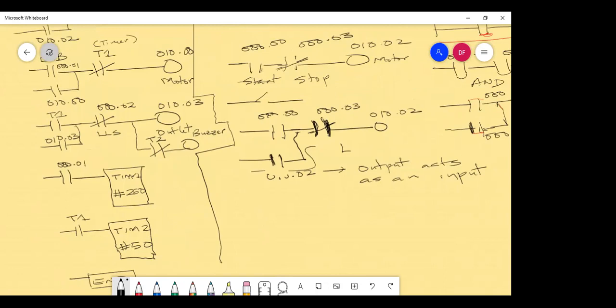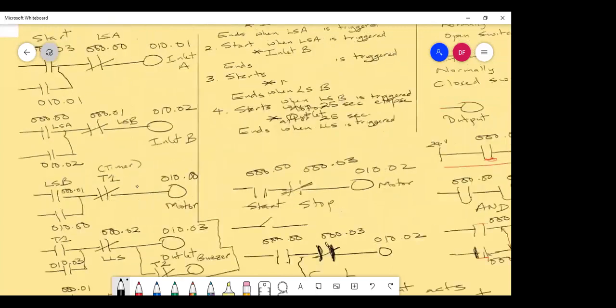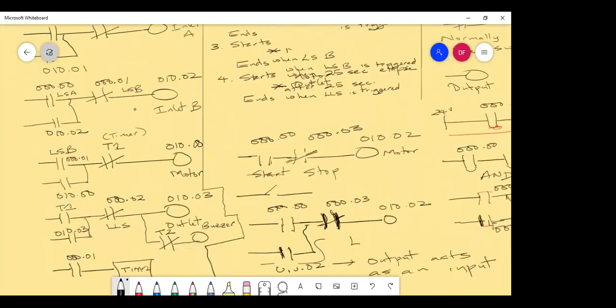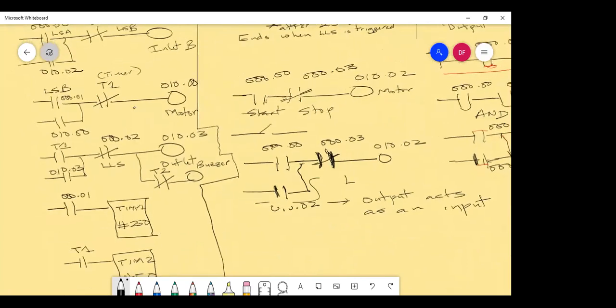And there are other PLC programming things that need an end or else the program won't work. This one doesn't need an end, but for good programming practice, we're putting in the end just the same. Now, so this would be our program. So we would simulate it and run it and see if it runs to specification. And then we would test it on the real thing.